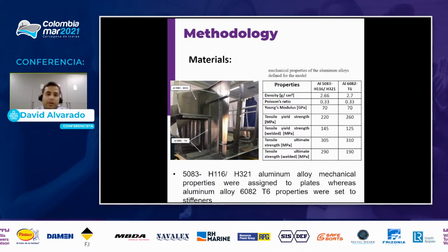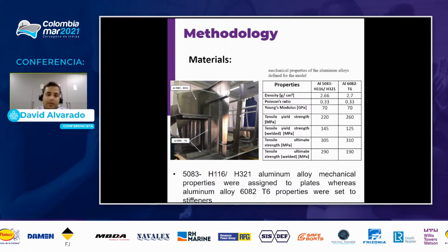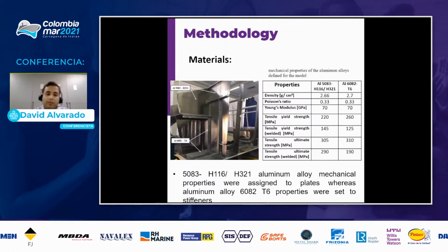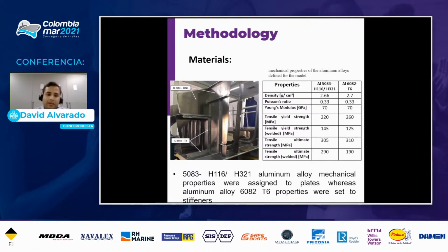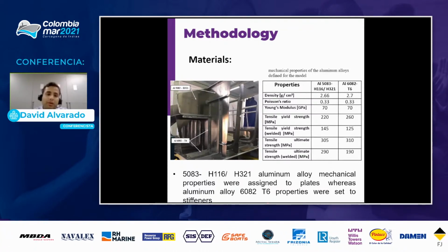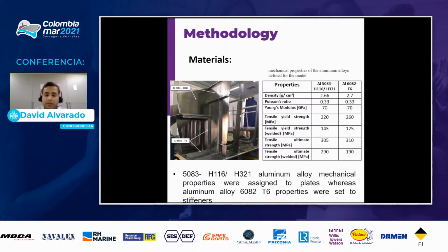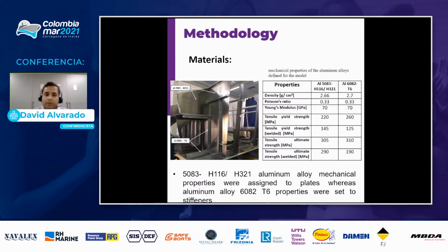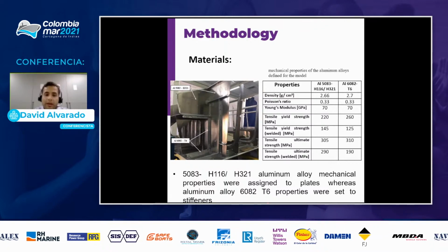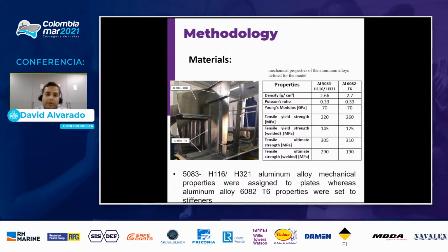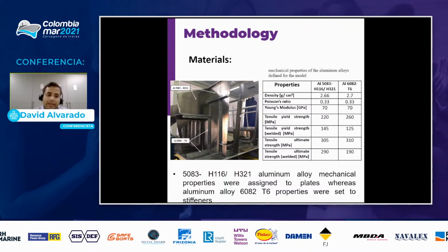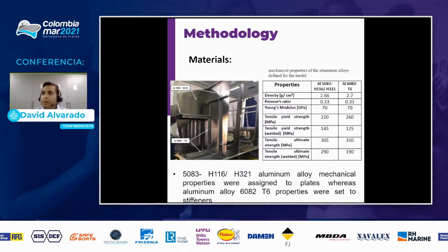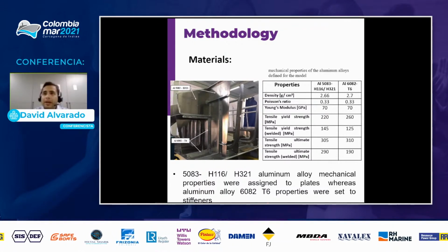For this boat, we have 2 types of aluminum. 5083 H321, which is hardened aluminum, and aluminum of the 6000 series. H321 is used on plates, bulkheads, liners, decks, and frames. And the aluminum profile of the 6000 series is used for the profiles.